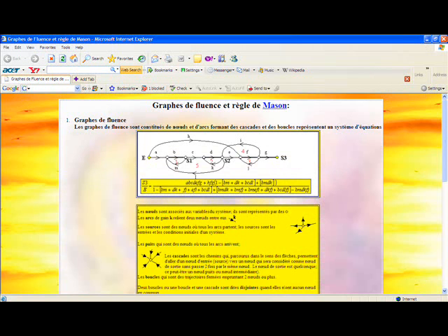As you see in this web page, the signal flow graph is represented by a block diagram in which small circles that you see here are called nodes. These nodes represent variables of the systems, and the nodes, as you see, are connected by lines called branches, which represent one-way signal multipliers. These small arrows on the line indicate the direction of signal flow, and a letter, for example here A, B, C or D, near the arrow indicates the multiplication factor.